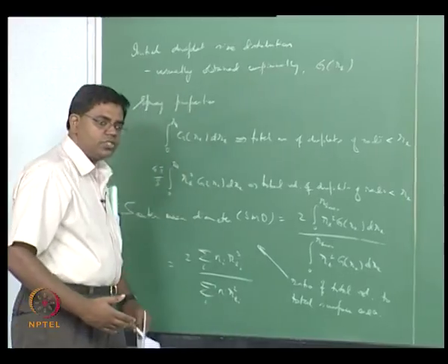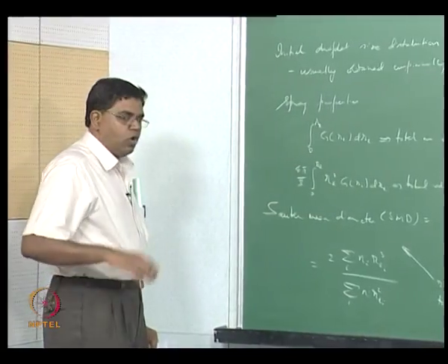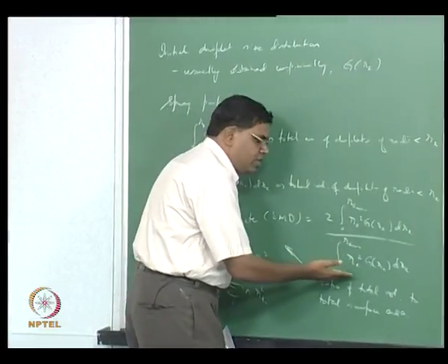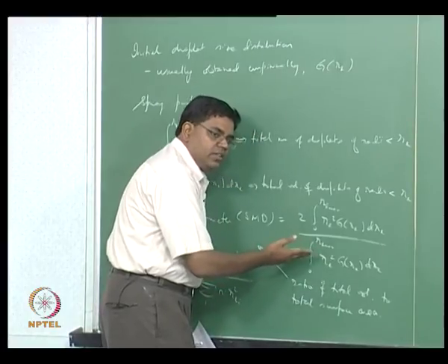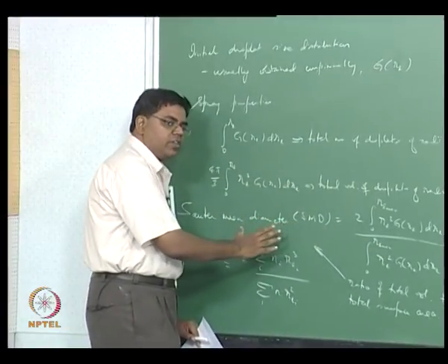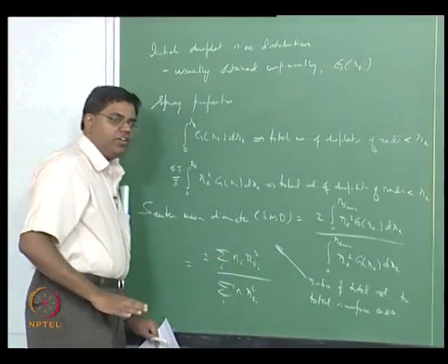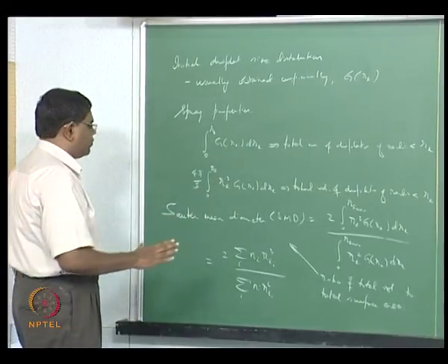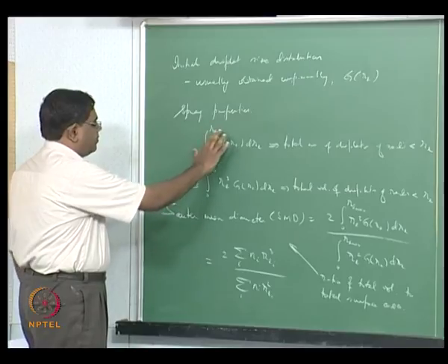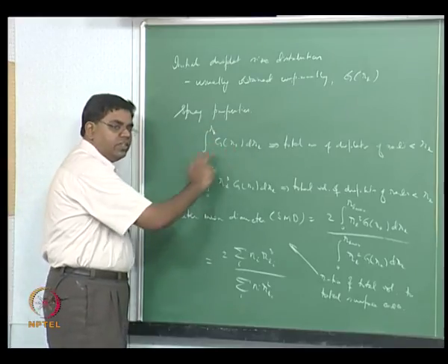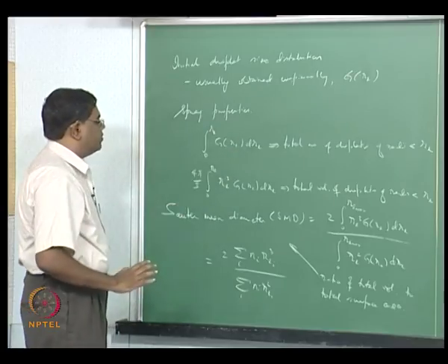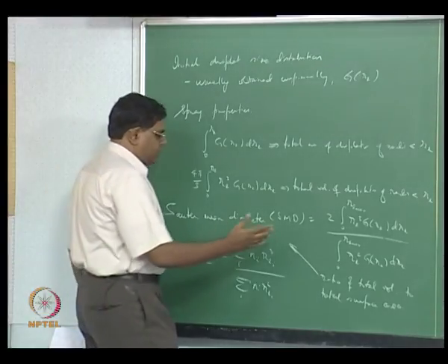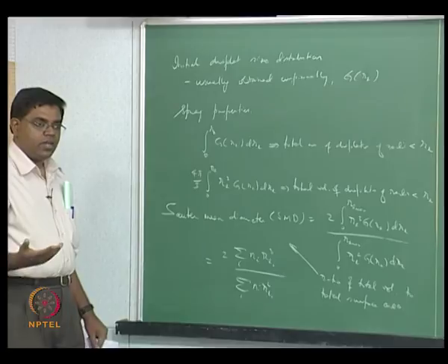Okay, so if you now have a larger and larger atomization done, of course the volume corresponding to it is also preserved. Typically if you have the same radius for all droplets, then it doesn't matter, you will get the same mean radius regardless of how you averaged. You did an arithmetic average, let's say, so for example this is the total number of droplets, and then if you now have an integral 0 to RL max, RL G(RL) dRL divided by integral 0 to RL max G(RL) dRL, right. That would actually be the arithmetic mean, and this would be the mean diameter. You could also have a weighted mean diameter and so on.